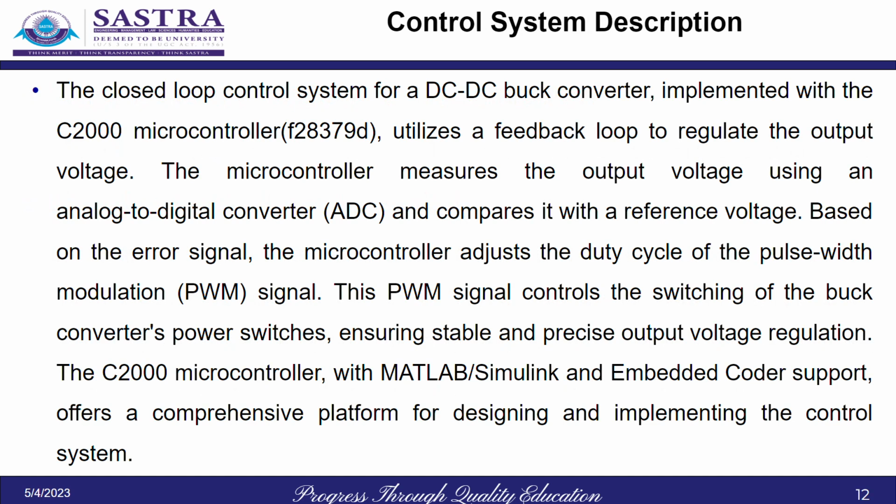We have actually used the F28379D microcontroller. It's a C2000 family controller, which we have used in our MATLAB modeling as well. This control uses an ADC through which the output voltage is sampled and given to the microcontroller, which is compared with the reference signal, and an error signal is produced. Based upon the reference signal and the output voltage, it produces a duty cycle which is fed back again into the switching device.